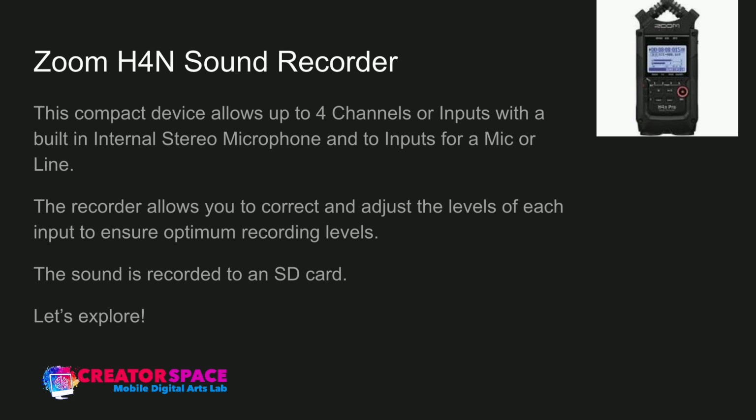Essentially, you're just making sure that you're not peaking. There's usually a red light if you're peaking, and you want to be kind of at -6 decibels as your top. So you have a little bit of headroom in case you go more than that. So 0 in digital, I always like to stress, 0 is not a good thing. If you come from an analog background, 0 was kind of like your -6 in a way, or -12-ish, between that area.